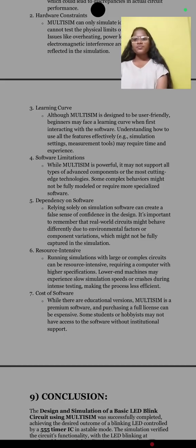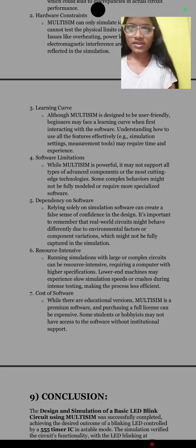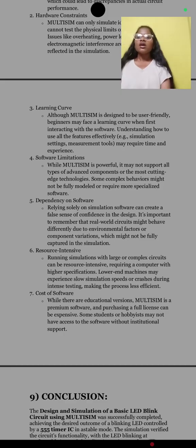Dependency on software. Relying solely on simulation software can create a false sense of confidence in the design. It's important to remember that real world circuits might behave differently due to environmental factors or component variations, which might not be fully captured in the simulation.